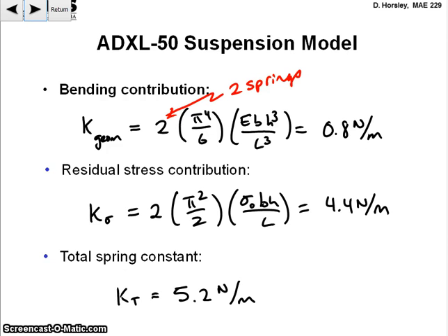And really for this device, we should think of this as almost more like a string in tension. Strings have no stiffness on their own, right? So there's no geometric stiffness to a string. We all know this because you can dangle a string from your hand and it doesn't have any stiffness. It's only when it's under tension that we get stiffness. And so this part here is that tensile stiffness component, and it's the dominant part of the stiffness in this device.